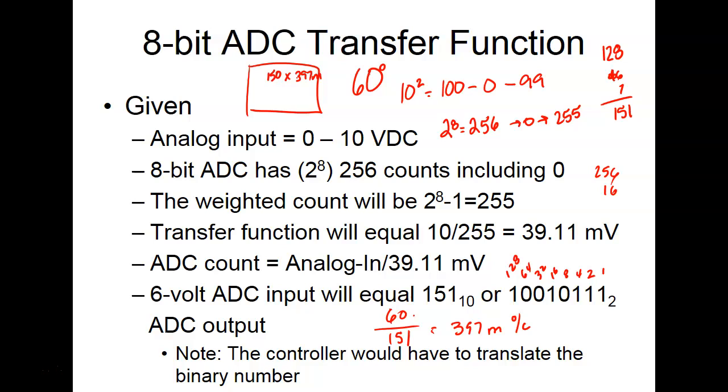This is also true on digital to analog converters. If anybody's had AC and used our digital scopes out there, when you look at that sine wave real close, you can actually see it moves in little steps. Because it's going through an analog to digital converter, it's not perfect, because we have a space between the steps.